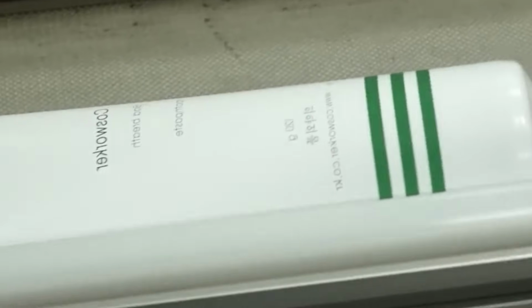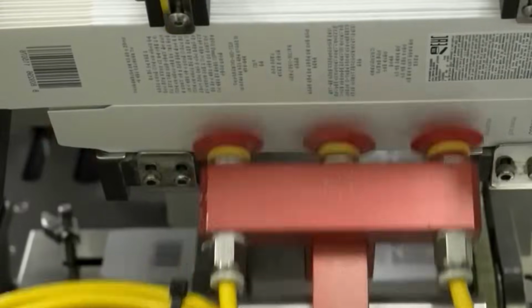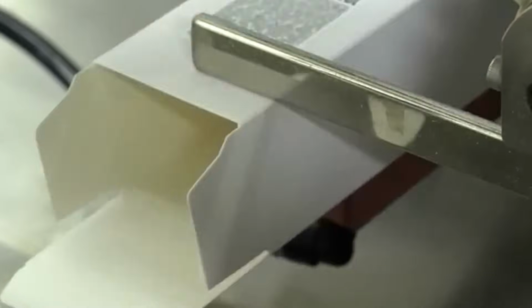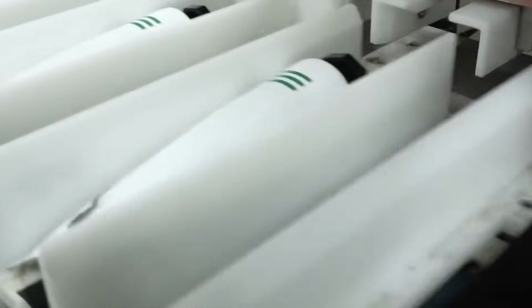Once the batch reaches target viscosity and homogeneity, a recirculation loop begins. The mixture is pumped through inline homogenizers or colloid mills to further reduce particle size and eliminate agglomerates. Homogenization shear rates exceed 10,000 s⁻¹, providing a consistent microstructure.